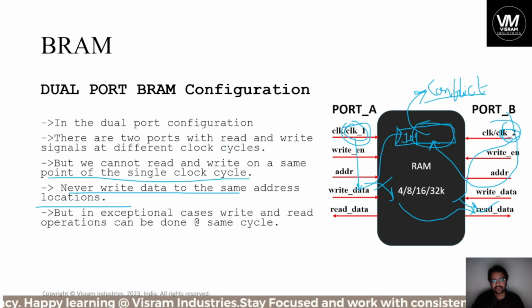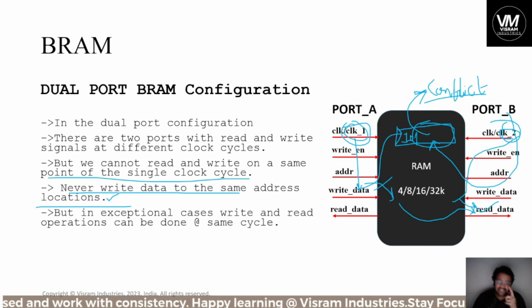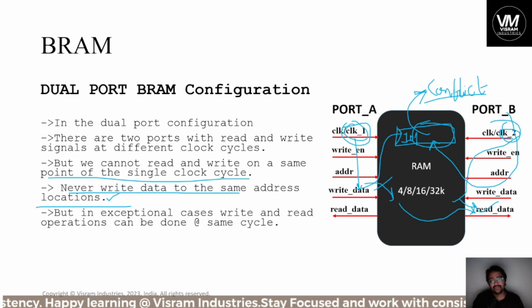Conflict, that can be conflict. So never make those kinds of mistakes if you are writing BRAM configurations. Usually you are not bothering about Verilog HDL for these BRAMs, whether it might be single port or dual port. The machine does the task, like EDA, you have to generate the Verilog HDL for it, and in larger complex designs, after you generate it, you need to verify it. Until you verify, there is no confirmation of using that generated Verilog HDL file in your design.